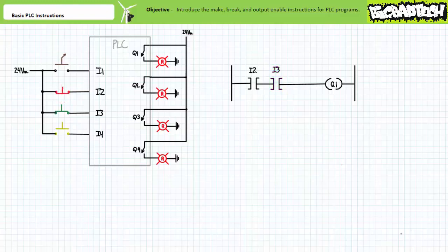The point of this lengthy analysis being that the electromechanical nature, normally open or normally closed, of the field input device has absolutely nothing to do with how the make or break instruction responds to the logical values received at the PLC input. This flexibility is a major advantage of PLCs over traditional hardwire relay-based ladder logic, where one is often constrained to the unalterable electromechanical nature of a particular device. PLCs additionally are far more versatile since they can be quickly reprogrammed without the time-consuming necessity of physically rewiring it.